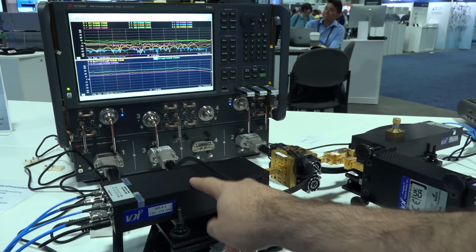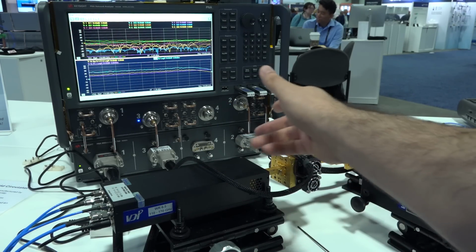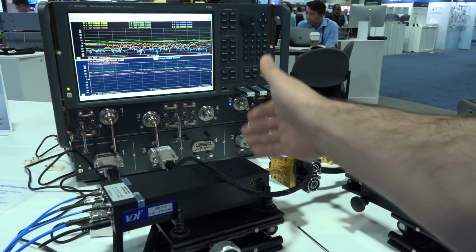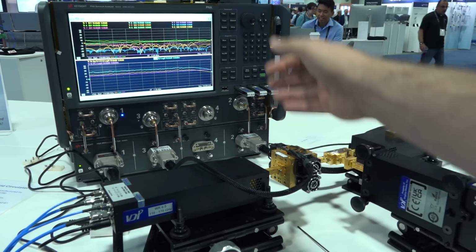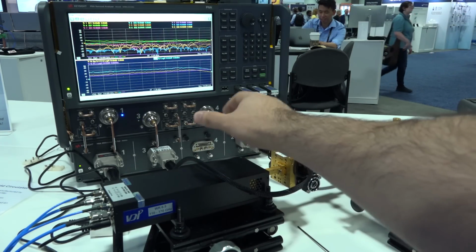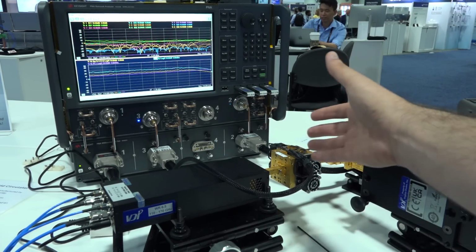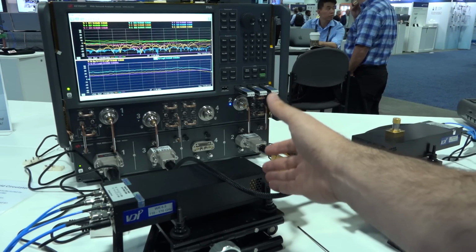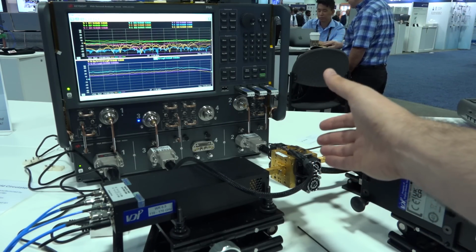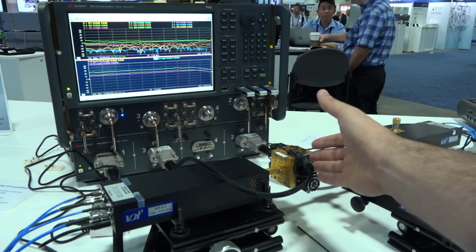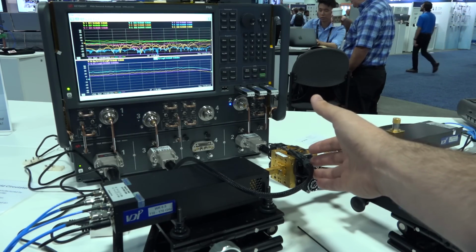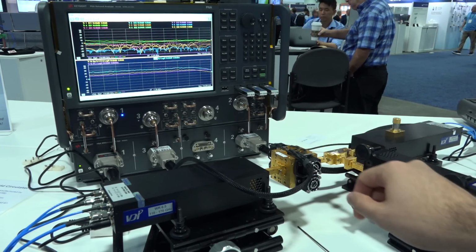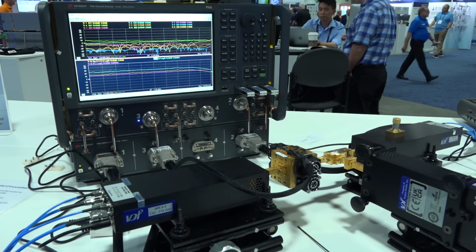Very nice. The new versions of the WR6.5 do have indium phosphide power combiners at the output as well. There are now 20 dBm, and I believe there's another version of it that goes even higher. Very important to get high output power from network analyzer extensions, because you often are measuring passives and you may have a lot of loss. And a lot of power also means that you can do power measurements and do OIP3 and compression measurements, actually be able to drive amplifiers that typically don't have a lot of gain into compression directly from the unit without an external PA. So very nice and helpful setup.